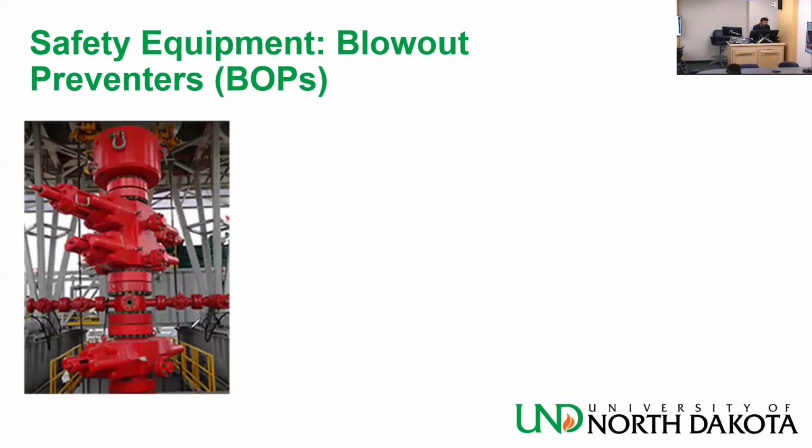For instance, this one here might be a pipe ram. Then one of these must be a pipe ram too. So if the tool joint is here, and it needs to go through this to go down, I need to open this pipe ram. If I have this open and this open, I lose control of the well. It's no longer shut in.